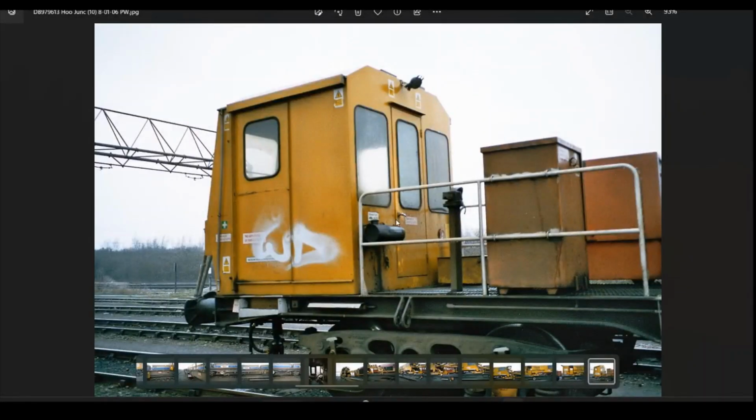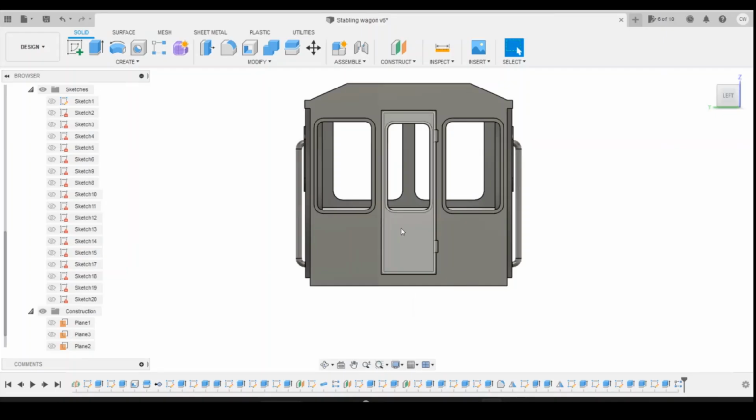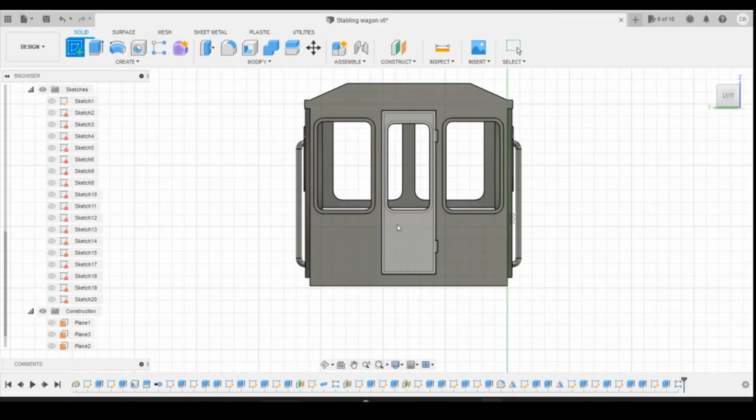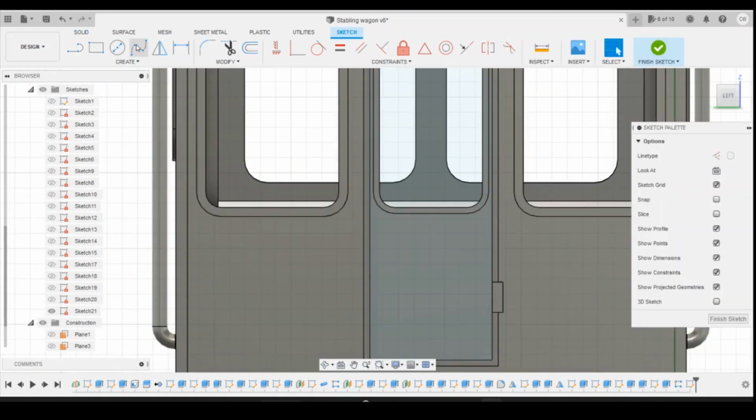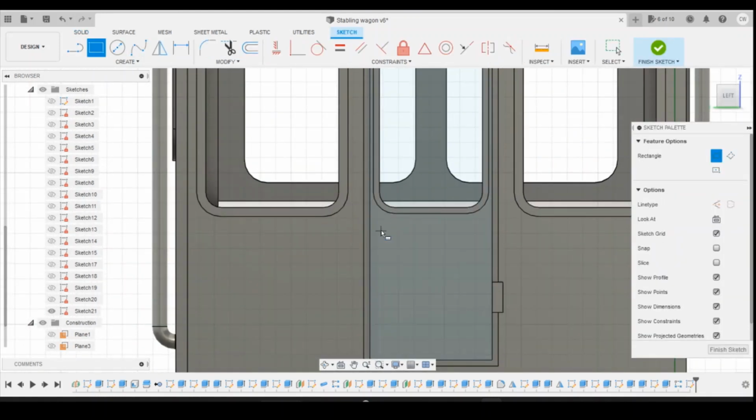So now the next thing we'll draw is the door handle. Again, I'm not going to do it in too much detail. I don't want to draw it as a proper handle. I'll just draw a normal rectangle and engage. You're not going to see the size of it. So I'm just going to draw a sketch and a rectangle size just below, like this. And we'll go for, sorry, 1mm on the length and 0.35 on the height.